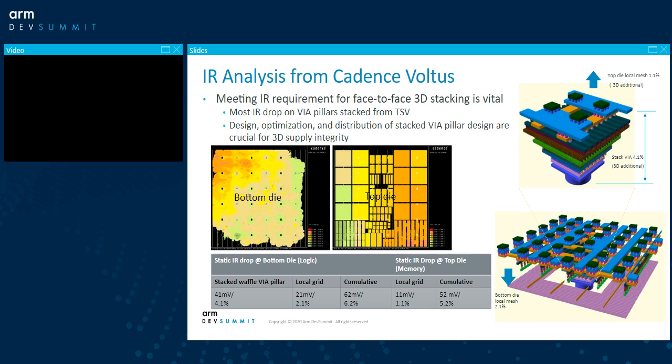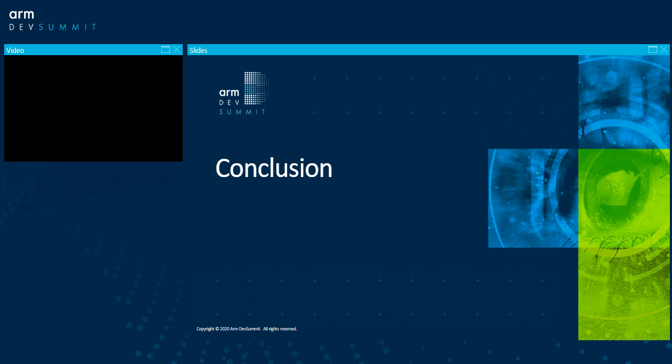So I think how to optimize this via, and also to effectively increase the TSV, without significant impact on PPA will be our primary focus to explore the feasibility of a 3D folded CPU implementation.